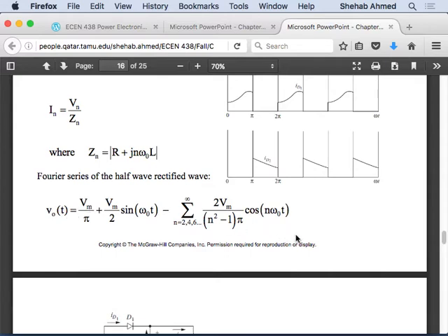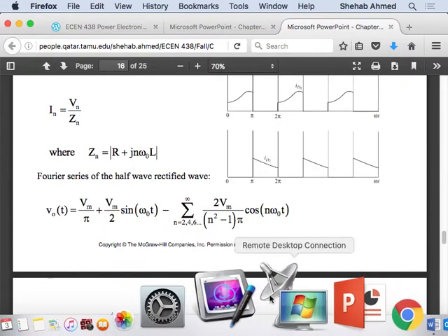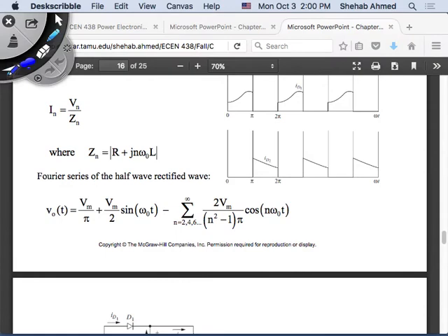They take this equation and find each corresponding harmonic. So they take the average value divided by the resistance. They take the fundamental divided by the value of the impedance at the fundamental frequency. Third harmonic or second harmonic, voltage divided by the impedance at the second harmonic. So that's example 3.7 in your textbook. I will not do it here since there's a good example in the text.